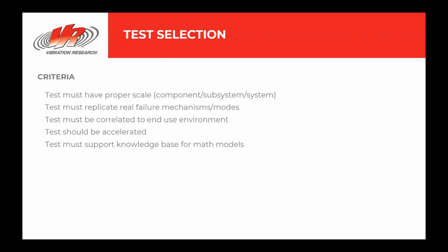One of them would be HALT or RFMPT. It's a highly accelerated life test or a rapid failure mode precipitation test, in which we identify latent failures and fix design early. It's quick and dirty, it's generally not correlated, and failures may be foolish or real. But it's an opportunity to find things that could break that we could fix before we get into the longer, more detailed correlated tests that prove out our design.